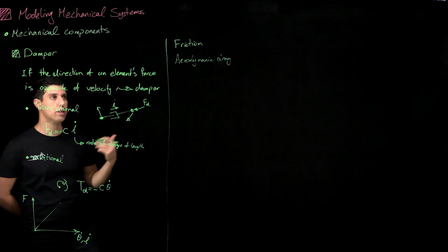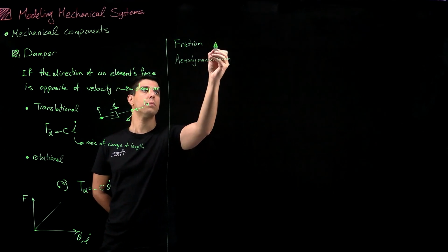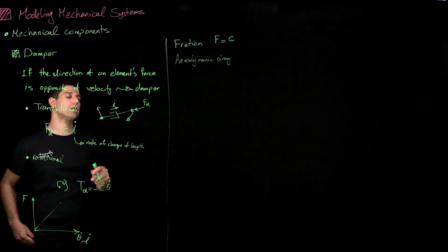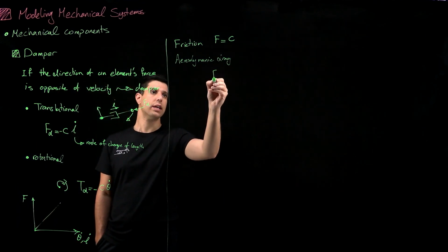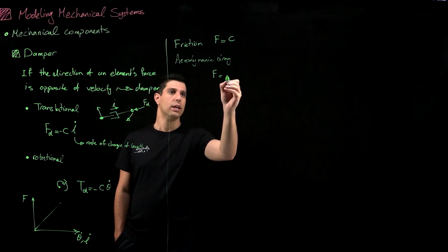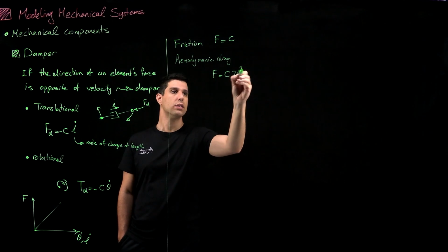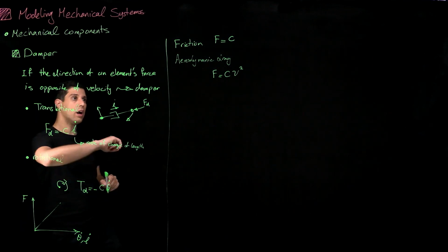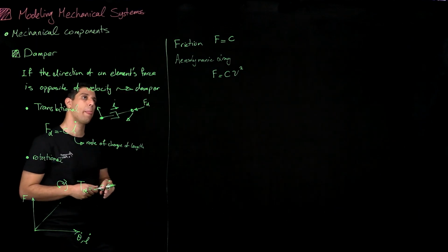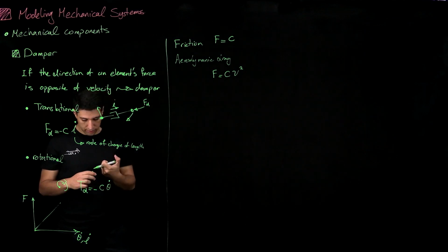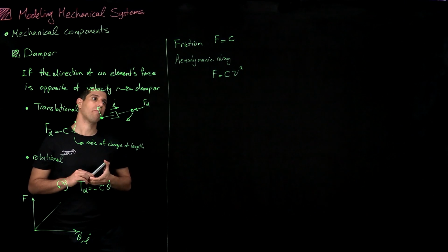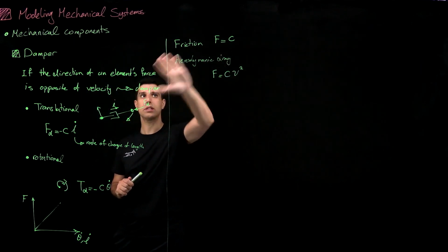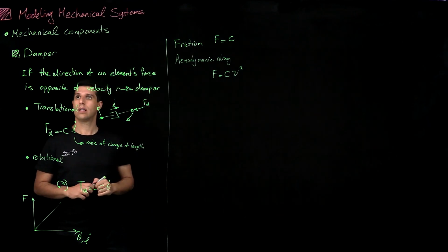The force is always in the direction opposing the movement, but in that case, well, let me write it. Here, force is constant, or it depends on the compression of the two surfaces together. And in this case, force is some constant times V squared. So here we had only x, V or theta dot. Here the force changes with the square of velocity. Both of these are nonlinear forms of damper elements that can work in the same way as a damper, but we usually do not work with those in this course because they make the system nonlinear. We stick with this type.